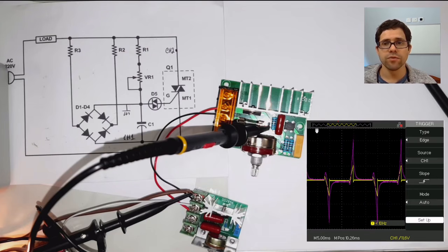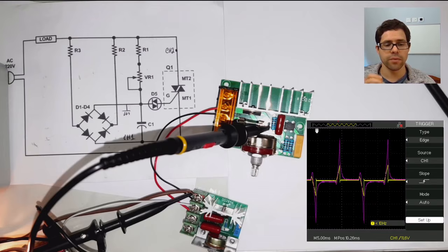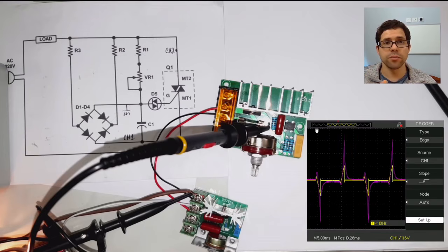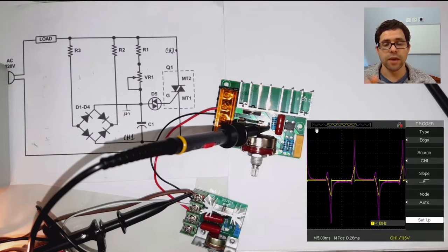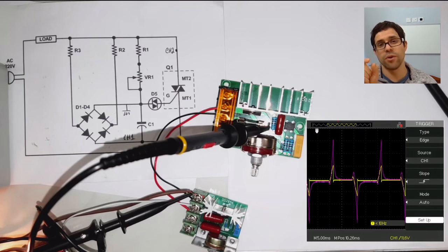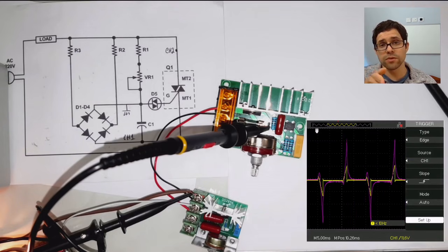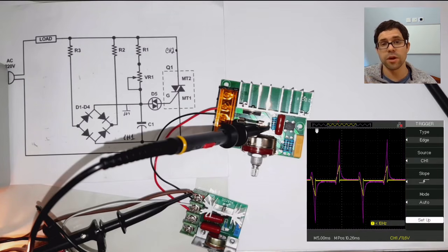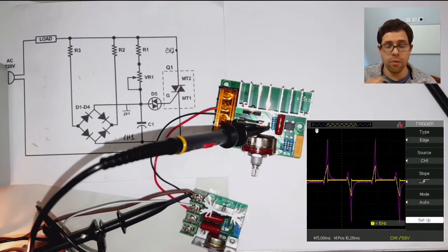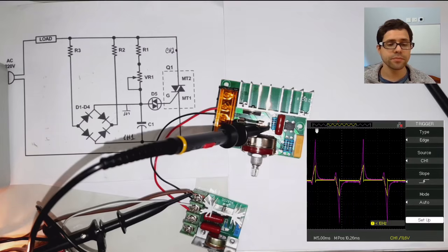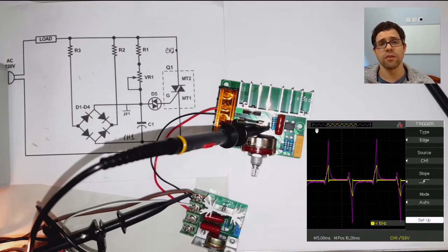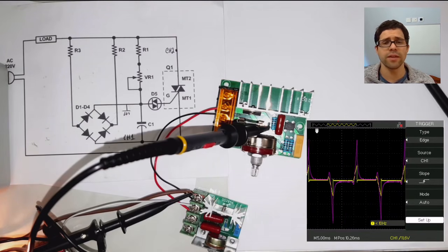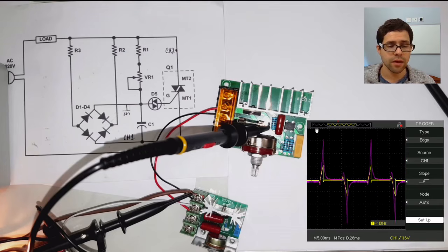It also removes this annoying popping effect where, when the triac starts operating, it has a voltage across it, and then if you try to dim the bulb all the way down, the bulb goes off, but then you have to put the potentiometer all the way up until the bulb comes on again, and then you discharge it again. So when you first start, you have, for example, 20% brightness rather than 2 or 3%, which is not really ideal.